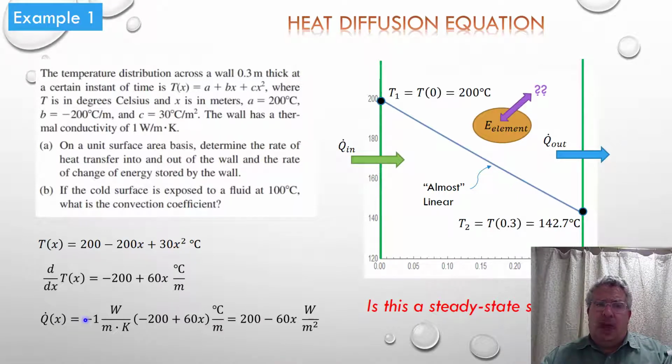So minus k. k is 1 watt per meter per Kelvin. And here is the term dT/dx, right? dT/dx now is an actual function. And if I evaluate it, my degrees C, right, this is a temperature differential, so degrees C and degrees Kelvin are going to cancel out.